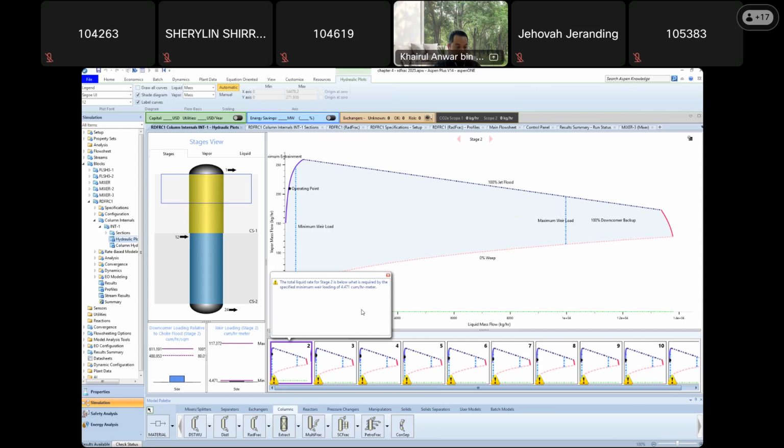This is the minimum acceptable volumetric flow rate of aerated liquid per unit length of weir, calculated on the basis of total liquid flow divided by total weir length. The default is 0.5 gallon per minute per inch. For a given liquid flow rate, the user modifies the geometrical spec of the tray.